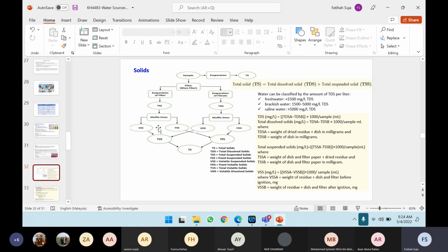So this is different, because the treatment of the different types of solids that you find in the characteristic of a water source is different. How you want to remove total solids, how you want to remove total dissolved solids. Maybe total solids is not difficult. You can have filtration, you can have a clarifier. But for total dissolved solids, there is a way that we'll study one by one, the unit operations that can remove the total dissolved solids.